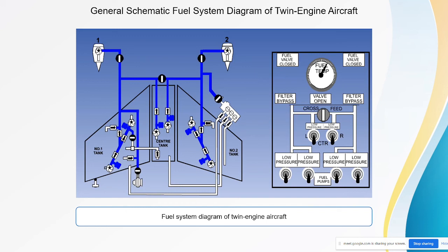This is what you guys normally just explain. So tomorrow you start with this, and then directly go explain where is the refueling, where is the fuel going. And tank one, tank two, and if the pump is running, where does it supply, how it supplies to the engine. That's the main thing.